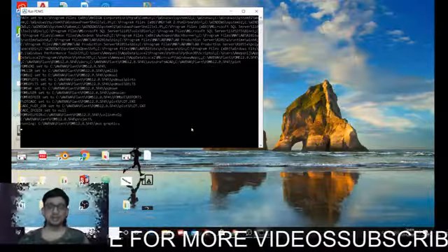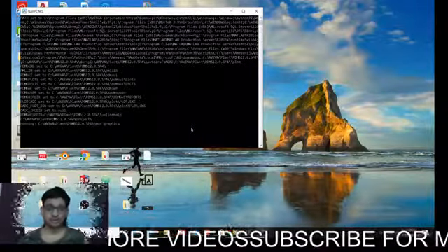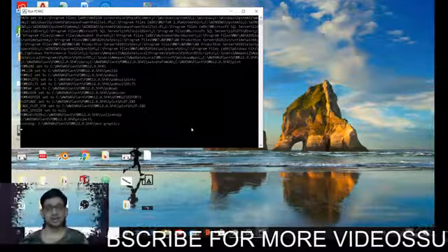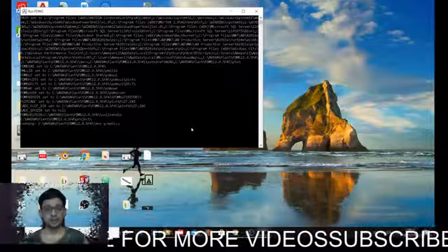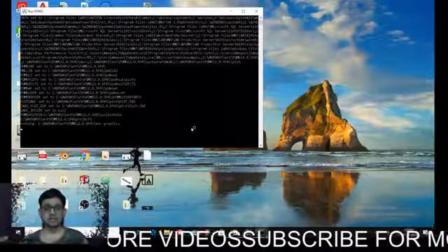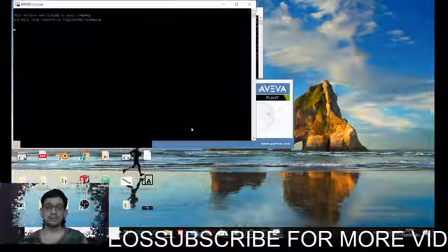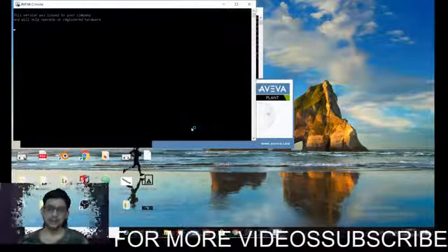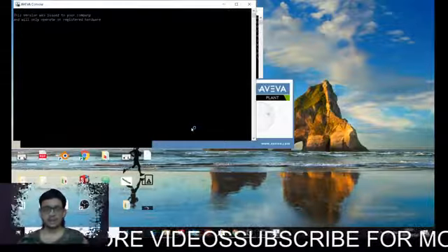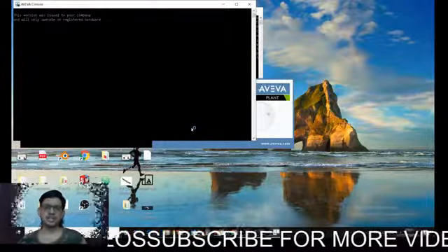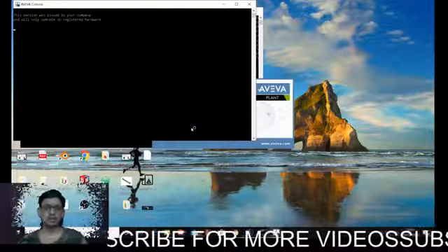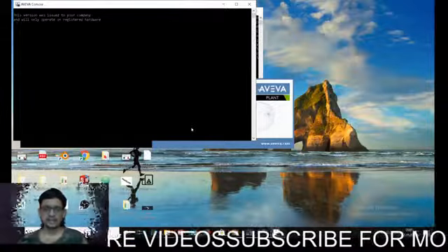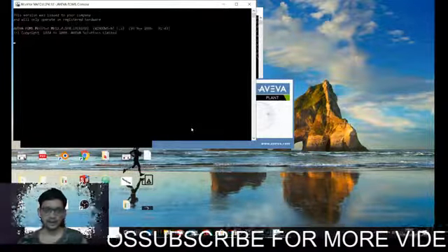Now PDMS is basically a server based software. So there will be one server administrator, and a username and password will be assigned to a person. Right now in our system for practice we are using PDMS as a normal standalone software. So we will be using sample as the username and password. That will take some time for initialization, so just wait for the login window to pop up and then we will discuss what kind of things we need to enter there.